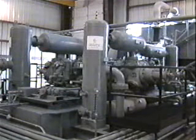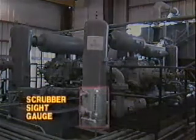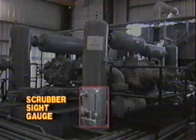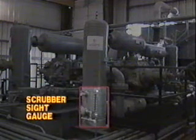There are additional indicators that can tell the operator problems are about to occur. For example, there is a sight gauge on the scrubber that indicates liquid level. High liquid levels in the scrubber will cause a compressor shutdown. Sometimes there is a low level sensor that causes an alarm to sound or will shut down the compressor.